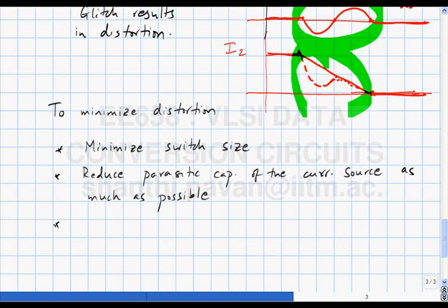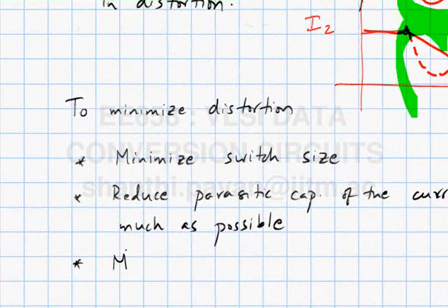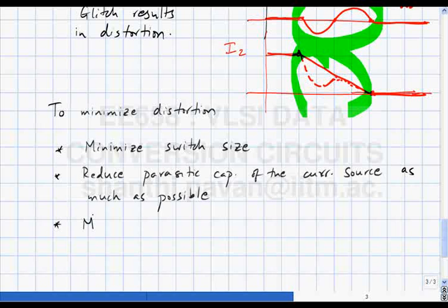And the third and last one takes care of minimizing glitch current. We know that glitch current is Cp dVx by dt. So there are three ways of minimizing glitch current. One is reduce Cp, one is reduce dVx by dt, and the third is to do both. This takes care of doing your best as a designer to reduce Cp by intelligent choice of device size.